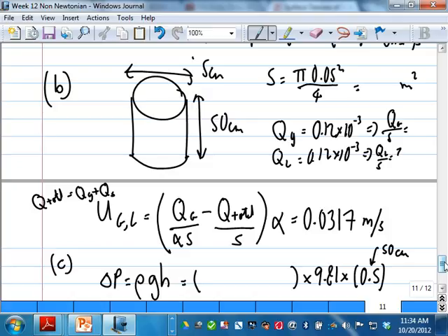Alright. So the pressure drop for a bubble column is normally just rho g h. So g no problem, h no problem, is that okay now? Rho has a slight problem, which flow to use, air or water. So we use the average by volume.